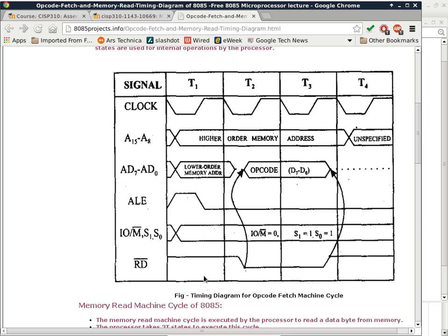And that's why we are not observing this kind of 10 clocks for one instruction and more. Instead, we are now observing multiple operations per clock because there's a lot of parallel processing going on inside the processor. And that's also why the memory bus becomes a big problem, because you cannot feed the processing elements fast enough in most cases inside a modern processor. And I think that's also partially why going beyond 4 cores per chip doesn't make a whole lot of sense anymore. What if you can theoretically put 16 cores onto the same chip? What would that buy you?